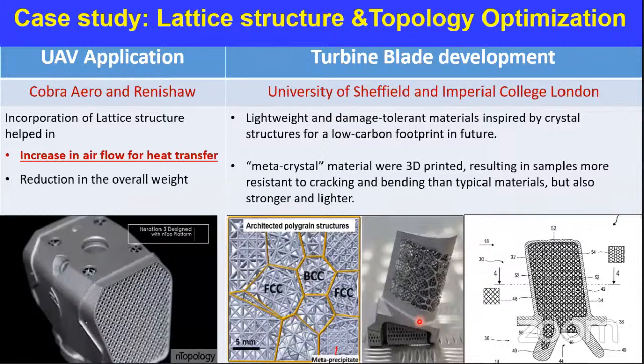Because in earlier existing turbine blades, we have different impingement techniques as cooling systems. So what are the challenges we need to face in case of AM technology? See, for example, in terms of the cooling holes which we can provide, for the turbine blades itself. One thing is that if you can have these kinds of lattice structures, no more is your entire blade solid.